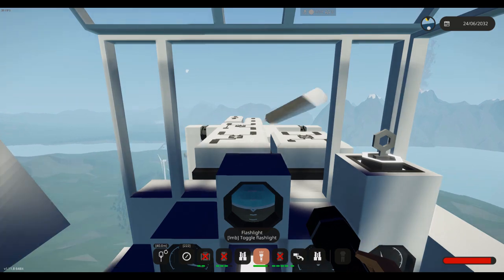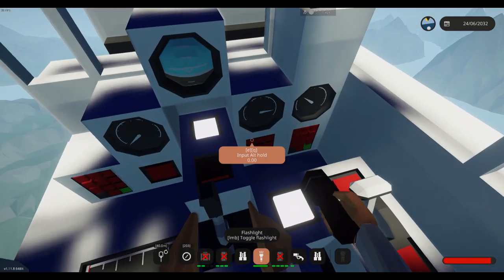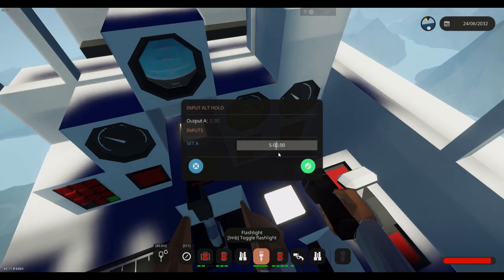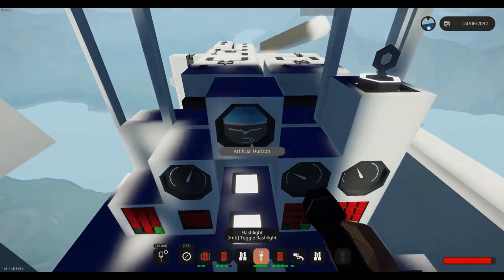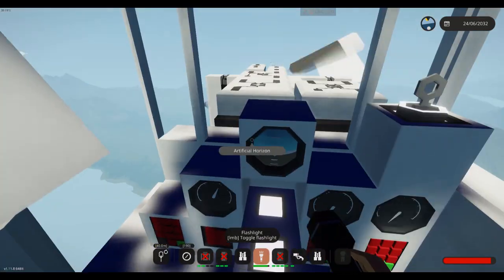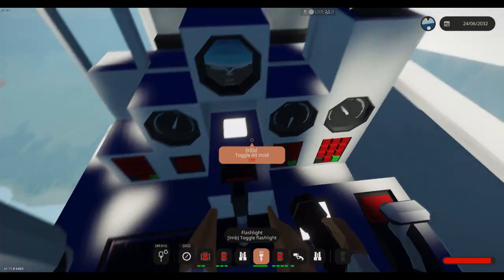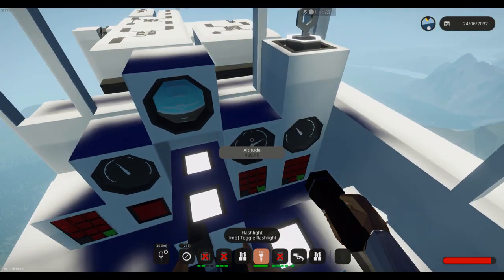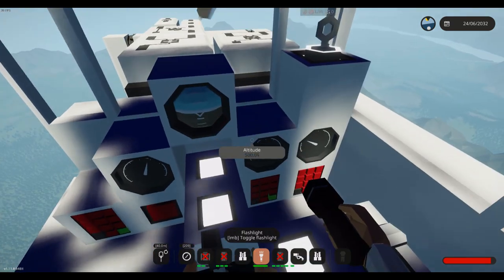Let's make sure we put our altitude at something stable, and this will help us visualize that our bank angle is working properly. So we're going to hold at 500. Turn that off, go a little bit lower, and right there. Hold there. Okay. Let the PID do its thing. Center. All right, so our altitude's fine.